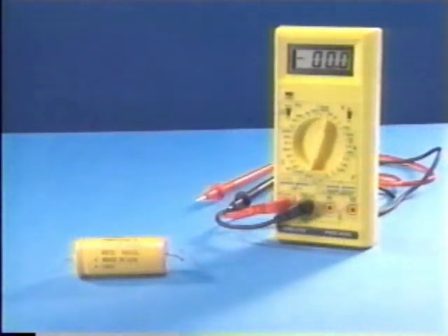A high voltage or any high-value capacitor can produce dangerous electrical shocks and burns if mishandled. As a student or trainee, you should never handle charged capacitors without the immediate supervision of your instructor. Let's consider the proper methods for safely handling charged capacitors. Imagine that you find an unidentified capacitor. The best thing to do in order to be safe is to check to see if it's charged with your voltmeter. This procedure assumes that your voltmeter is capable of reading the highest voltage that could exist across the cap.